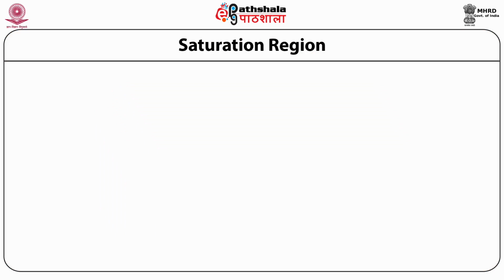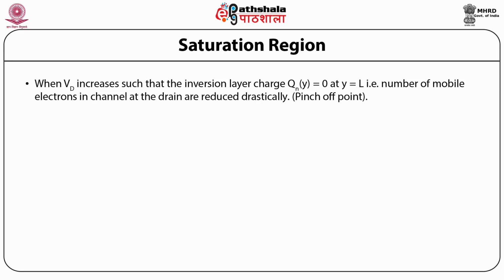Let us now discuss the saturation region. When Vd increases such that the inversion layer charge Qn equal to 0 at y equal to L, that is, the number of mobile electrons in the channel at the drain is reduced drastically, we can say this is the pinch off point.